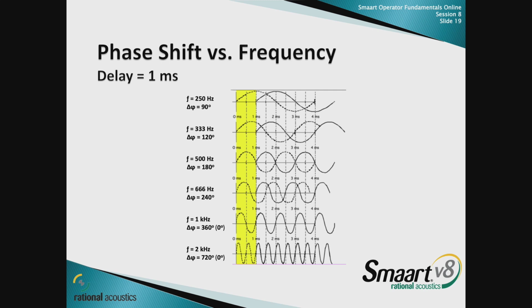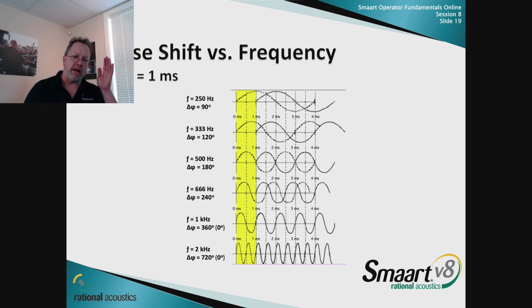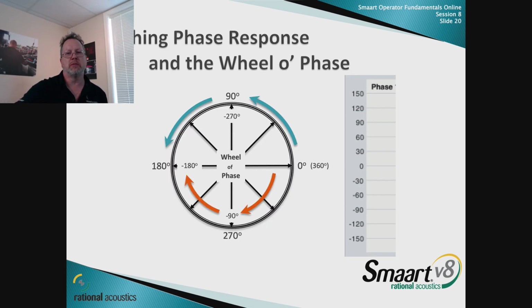We're going to take a look in the next episode at the mechanics of a comb filter, and this is going to play directly in, where the comb filter frequency is going to be 1 over the time offset. So if the time offset was 1 millisecond, 1 over 1 millisecond is 1 kilohertz, so we'd see addition every time it comes back around to 360, and we'd see cancellation halfway in between. So we'd see addition at 1K, 2K, 3K, 4K, and a subtraction at 500, 1K5, 2K5. We'll get into that. A lot of you guys have seen this before.